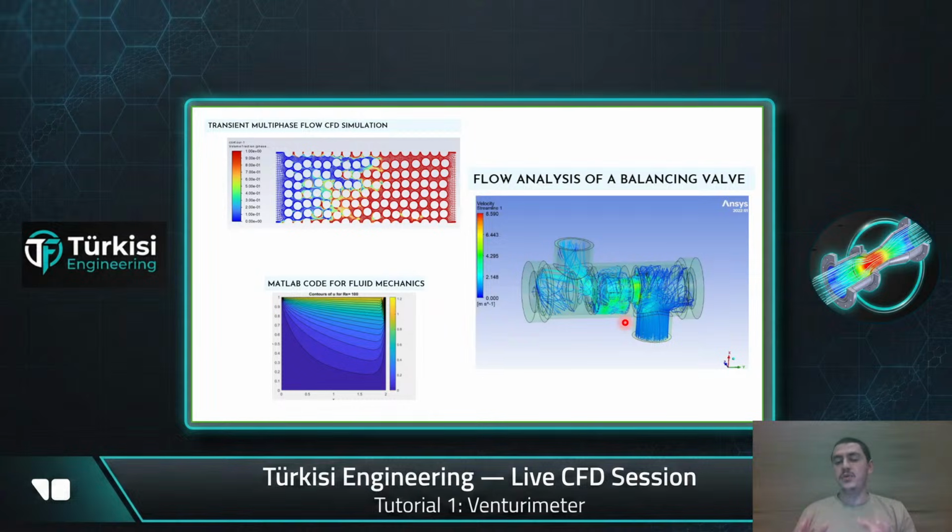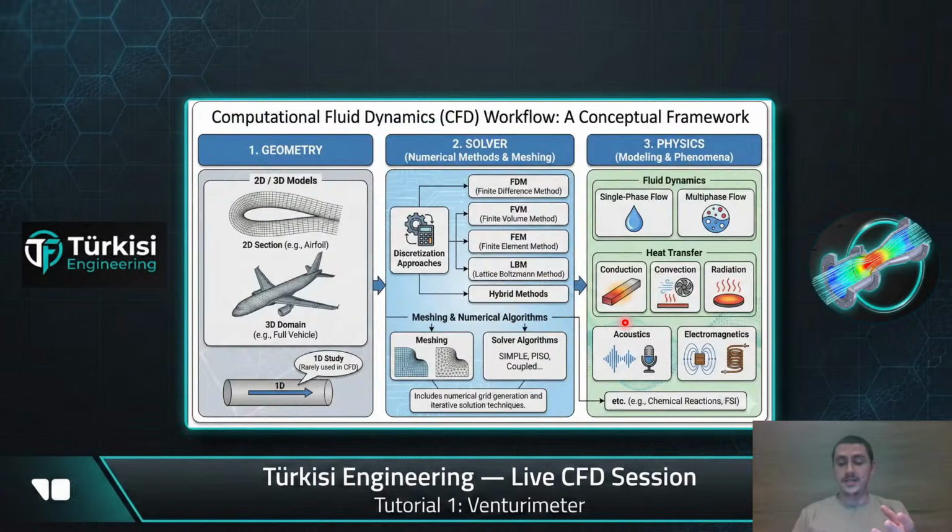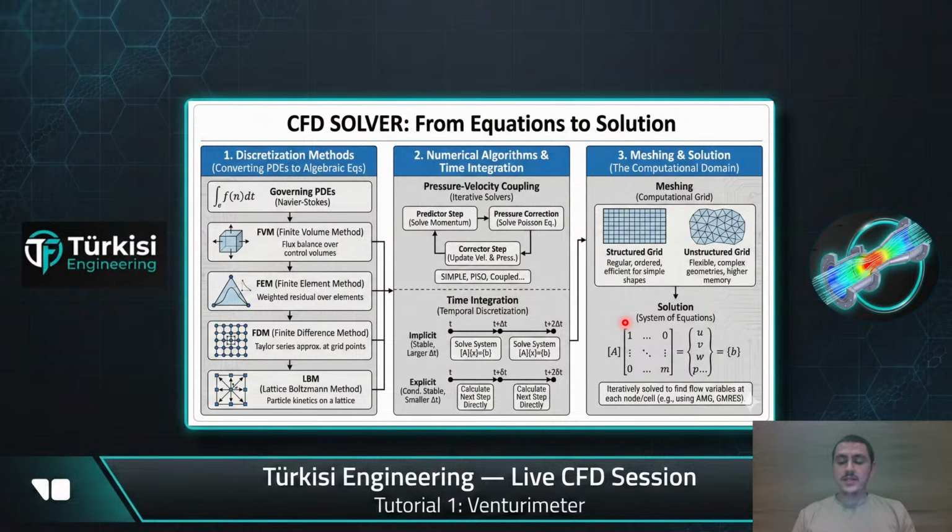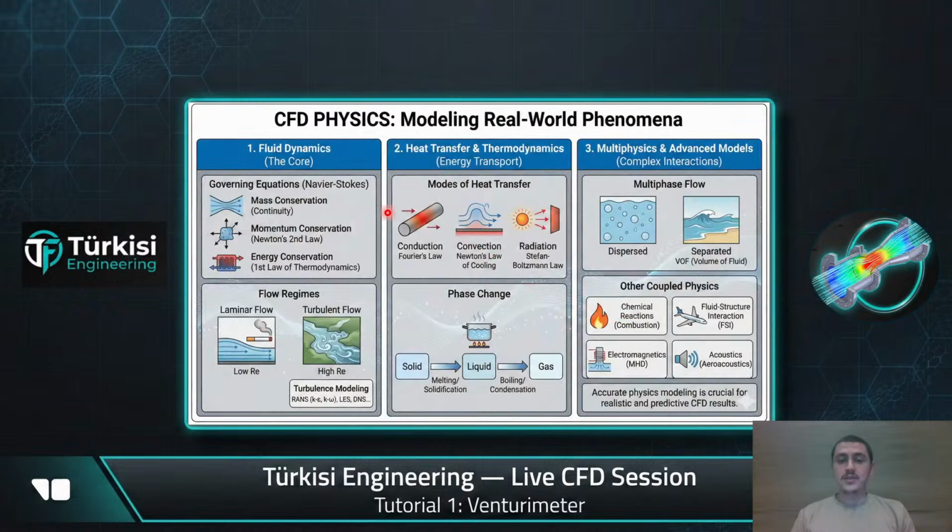It's just pure hydrodynamics, okay? So you don't need to use heat transfer here. And there is no phase change, okay? Water is not evaporating, there is no other phase included inside. So that simplifies your physics. No conduction, no heat transfer, and no phase change. You have only single phase fluid dynamics.